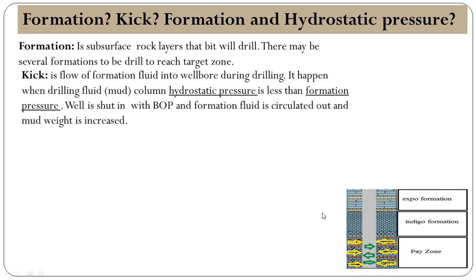Kick. What is kick? Kick is the flow of formation fluid into the wellbore during drilling. It happens when the drilling fluid or mud column hydrostatic pressure is less than the formation pressure. Well is secured with the BOP. Formation fluid is circulated out and mud weight is increased.